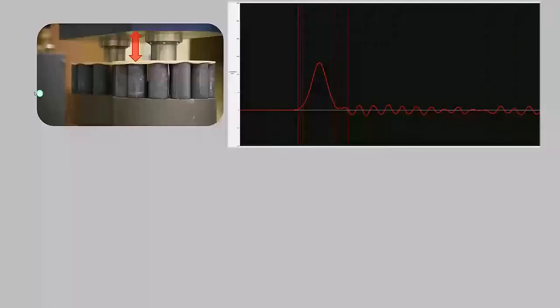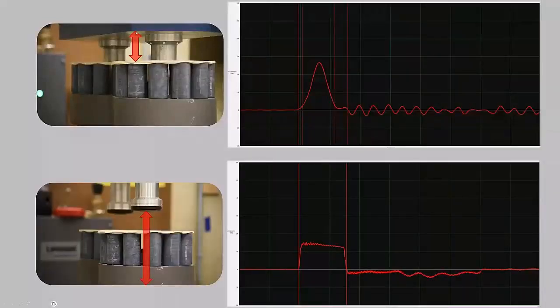So, to show what was in that video, the differences. Just to show again, the aluminum bottom of the table impacting against these Delrin programmers. This is just a thin felt material that's used in between the table and the Delrin, just to help eliminate some of the high frequency noise, the ringing that might occur if it wasn't there.